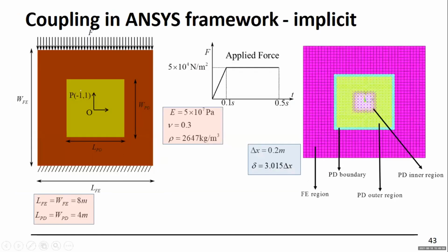So we have a plate, and this is the peridynamic region here. This is the finite element region, clamped, and then we're applying this dynamic load here, and then we lift it, unload it. As I mentioned in the previous slide, I have the region here, the non-ordinary state-based equilibrium equations derived by Silling. And this region here is the outer region. The equilibrium equations are derived by a peridynamic differential operator. And this boundary layer region is coming from the weak form of peridynamics. And we are using traditional elements here. There's no overlap region. It's basically direct coupling.